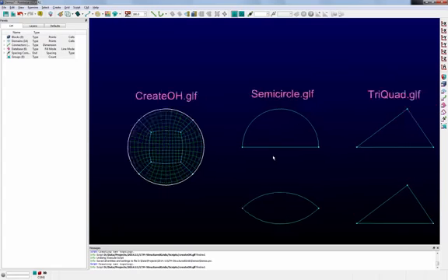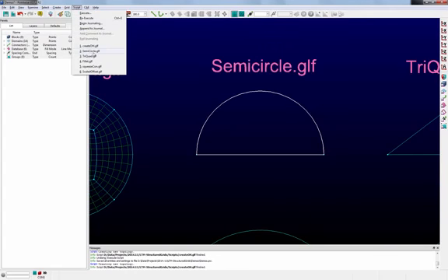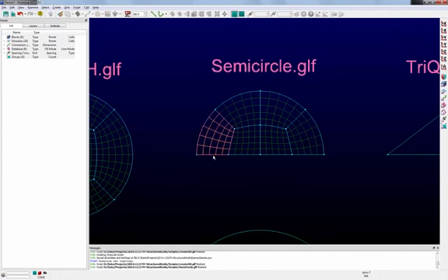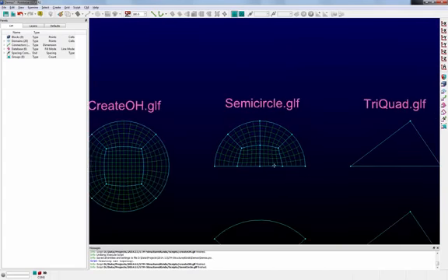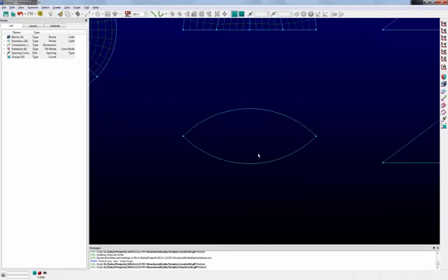Similarly, this sort of approach can also be extended to these half circle domains that consist of only 2 connectors. In much the same way, we're just going to highlight those connectors, go up to Script and run the semicircle script. The semicircle script doesn't require an input because the dimension of this flat piece actually dictates what your radial dimension can be. So whenever you run this script, it automatically determines that, generates the topology for you, and voila, you have your topology within a matter of seconds.